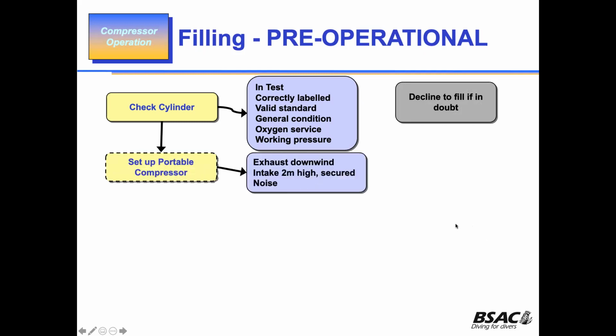Right. Set up portable compressor, exhaust downwind, intake 2 meters high, secure noise. Make sure that you've got earmuffs on if you're going to stand alongside it.